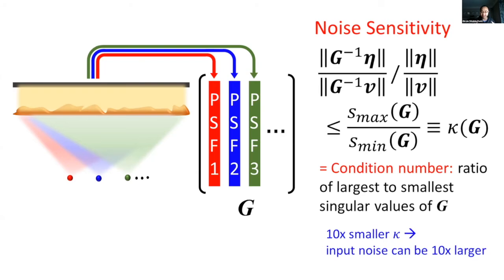Because this is quite important. So this measurement matrix G is, as I said, conceptually straightforward to construct. What you do is you show point sources one at a time, do your nanophotonics front end, and you measure the intensity pattern on your CCD sensor. Then you stack these point spread functions into a matrix form, and there you get your measurement matrix G.